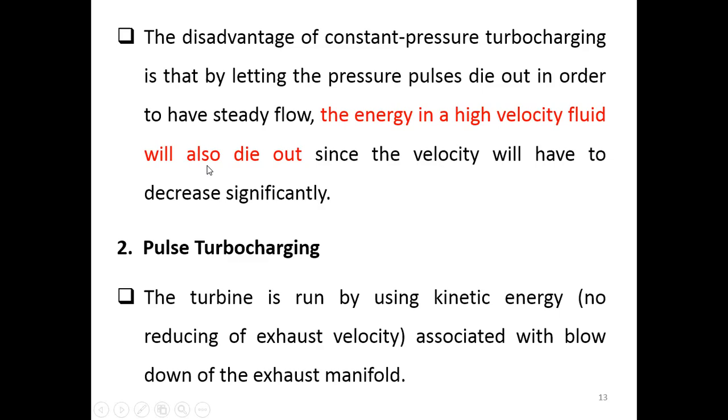The energy in the high velocity fluid will also die out, because in order to have a constant pressure, the velocity will have to decrease significantly. That means we have to let the velocity pressure die out, so we will have only the static pressure of the flow.